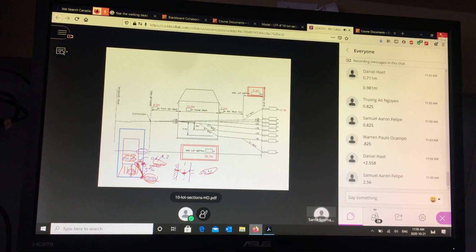So let's describe this one more time before we go on. If you know the elevation at the front and you know the elevation at the back, the difference, which is what this number represents, tells you what kind of design you need to perform. So if the elevation at the back was 3 meters higher than the front, then you would design it like this. Go up at 3% to this point here, go up at 3-to-1, and then the difference between this elevation and your existing ground elevation at the back would be the height of the wall. Okay? Any questions about that?